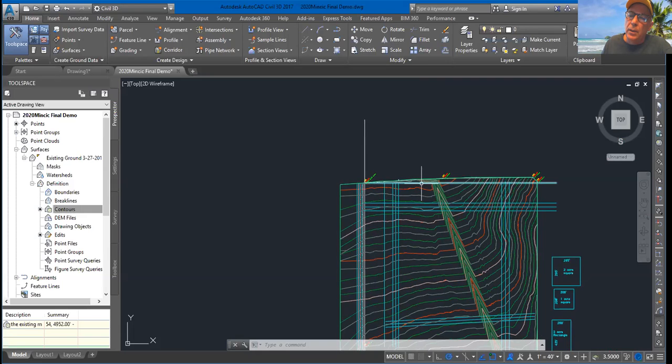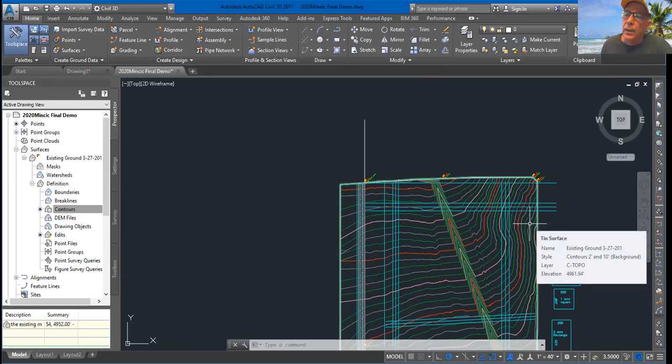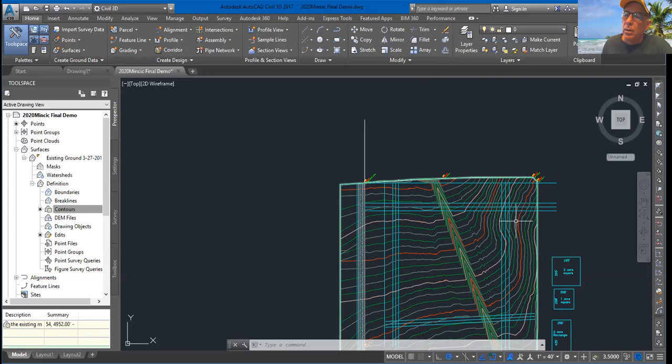So what I've done is I've simply offset this one at the 208, offset this one at the 295. I've then offset this one here also at the 295. Now, one of the considerations I'm making on these lots is notice how the contours are steeper right here. With the contours being closer and tighter together, I would expect this ground to be more sloping. Therefore, I would want larger lots. Therefore, the client could find a good buildable area within there. So that would be a consideration we would make.